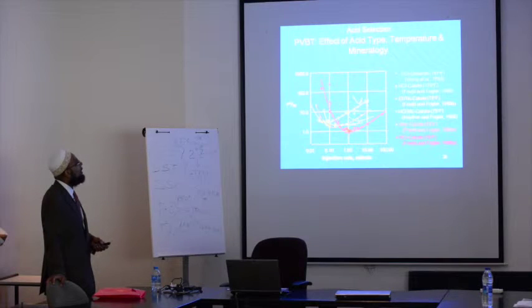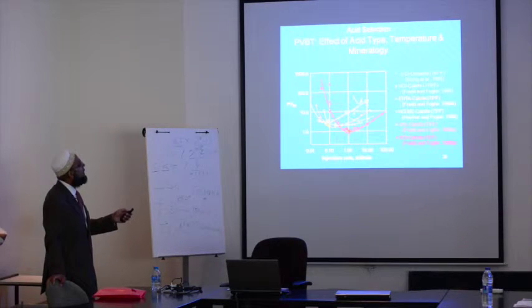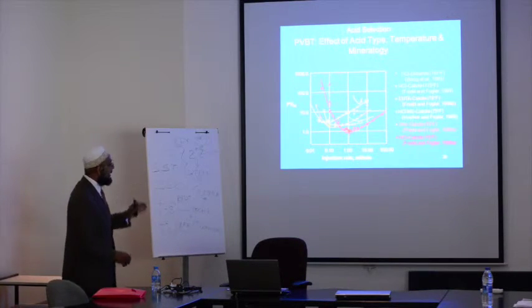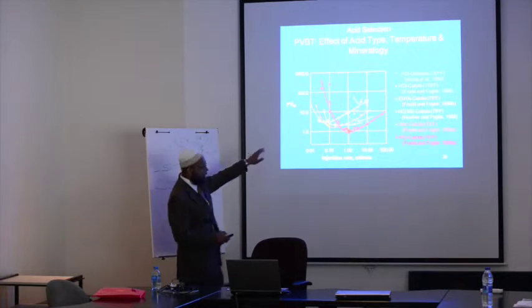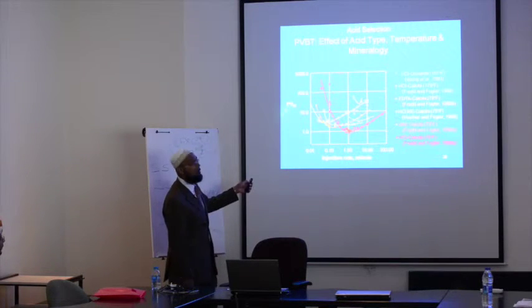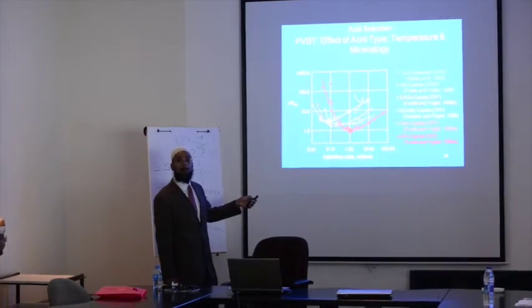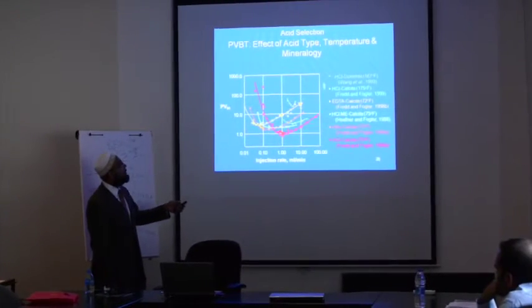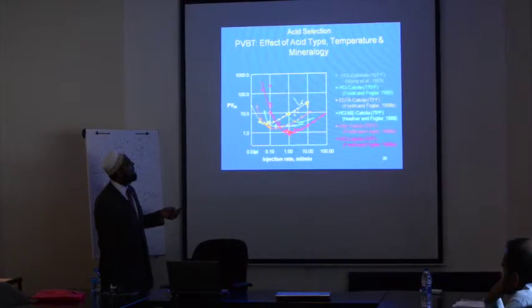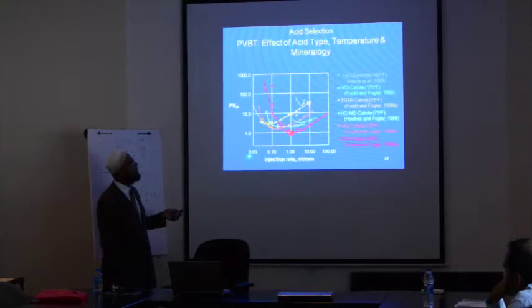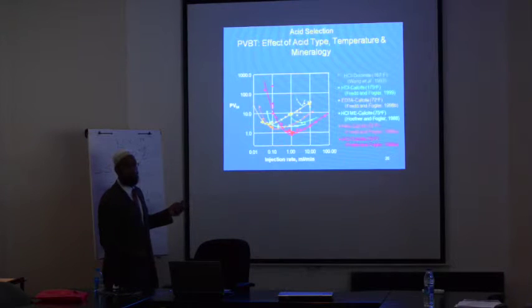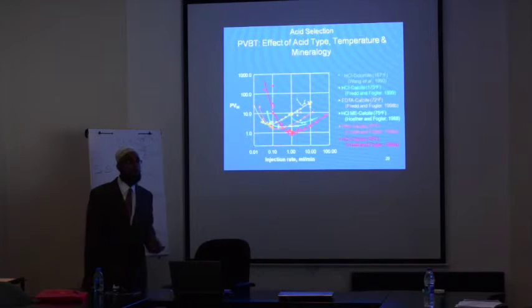Okay, so knowing your injection velocity, especially for the acid that you have selected, is really critical in designing and picking the fluid. And this plot is kind of a busy plot, but the key thing here is I have the same variable, pore volume of acid to break through versus injection rate, but this is actual data, right? And over several systems here, the key thing is this is a log-log plot. This is the only way I could bring them together.